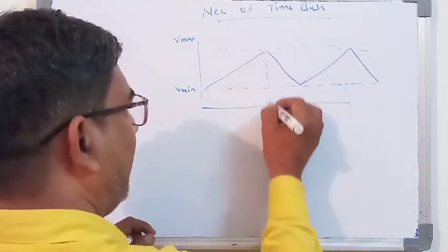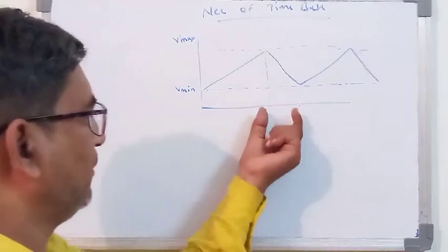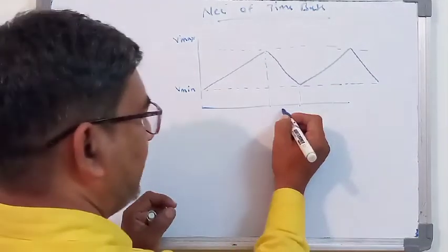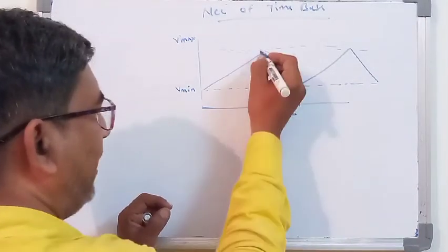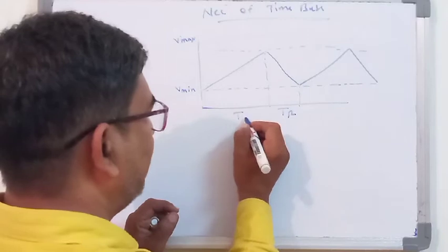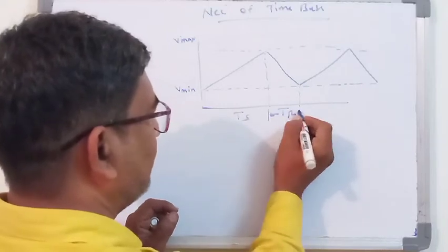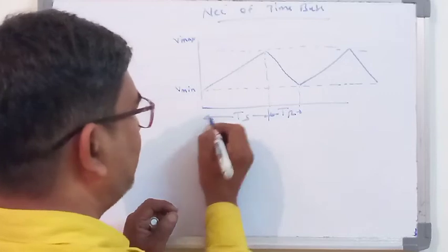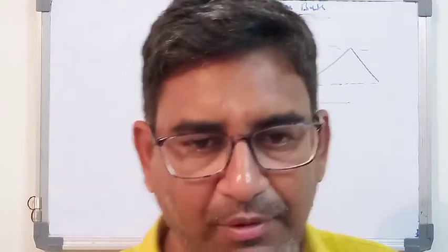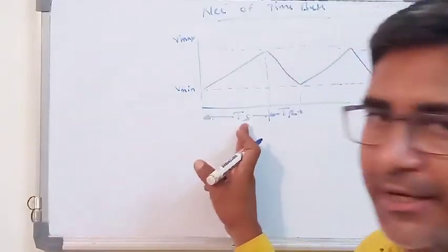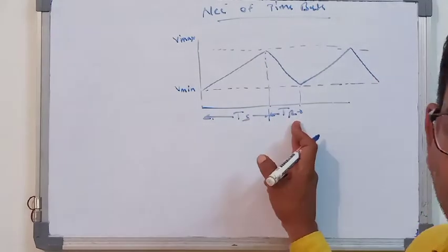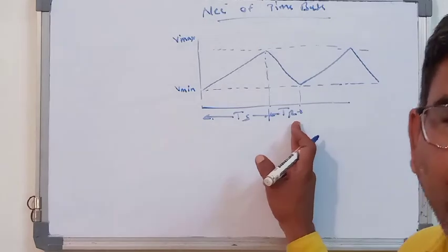Okay, so this part and this part is the part which has been used by us, and it is a TR. From here to here, the sweep start is indicated with the TS. So from this it is very clear to you that the TS value means the sweep time, and TR is the retrace time. This retrace time is also called the flyback time.